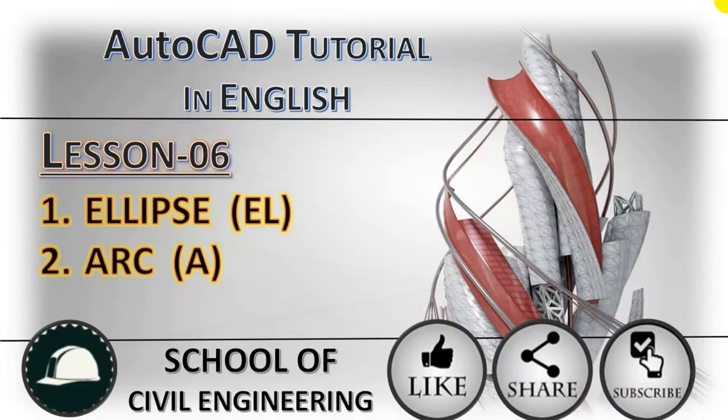As we have started an AutoCAD tutorial series in English, this is lesson 6, and in this lesson I'm going to discuss the ellipse and arc. For the ellipse, our command will be EL, and for arc our command will be A. Whenever I discuss any topic, I give its shortcut for AutoCAD; you can see it in the bracket.